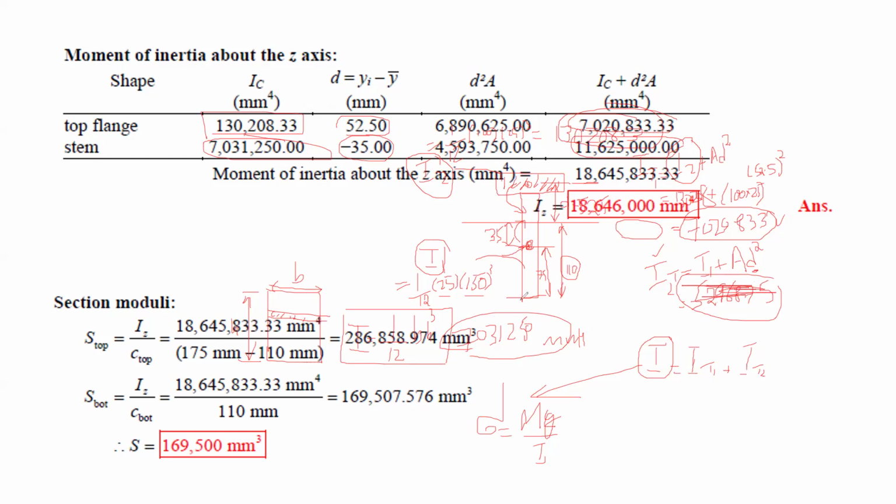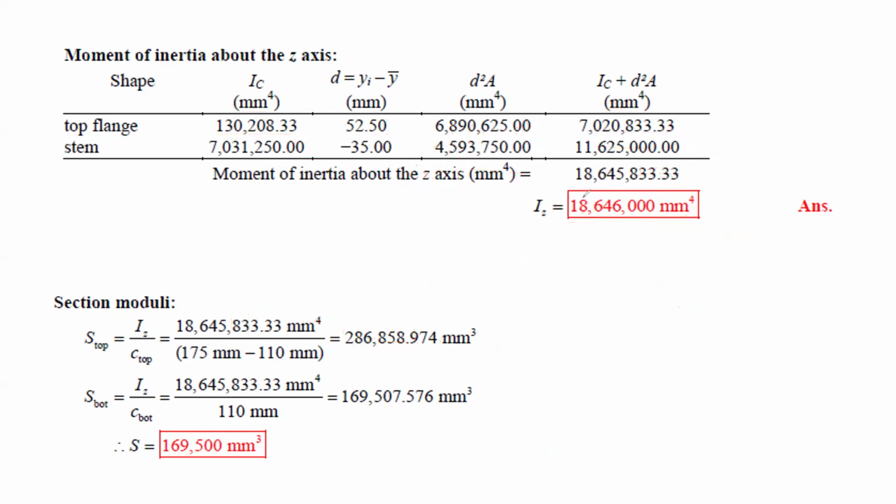Okay, should I erase the writing so you can see the table clearly? Yes, Professor. So you add this, and this is the value of I that is required in order to solve the formula or to process further. So students, I have told you what section modulus is. I will write it again. Section modulus is basically if you rewrite the formula and instead of writing y with respect to I, you just mention it like this ratio. This is called section modulus, right? Generally, this value differs based on whether you're looking at the upper area or the lower area, for example. So this value will fluctuate, right? And the lower value shows that this is the weaker side. The lower value is the weaker one, where it can easily bend, for example, or where it is weak. So we call it the controlling section modulus.